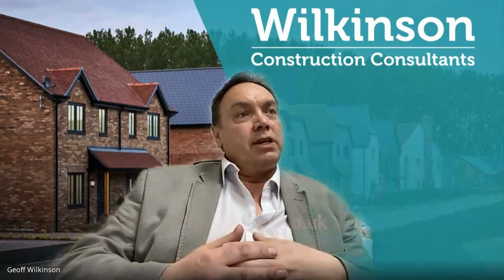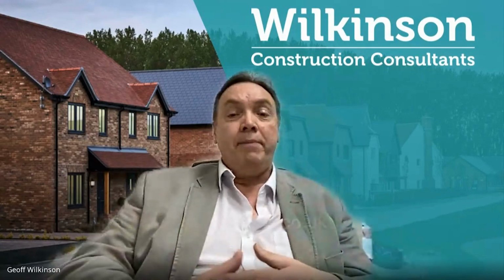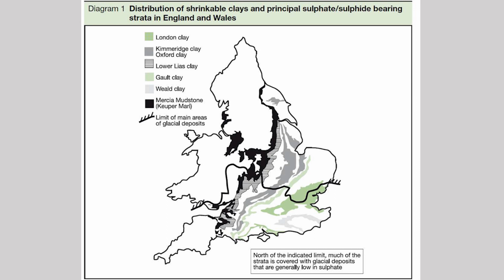One of the things that you quite often have is that the sites that are available are brownfield sites, so they'll have some kind of past history. It may be that they're adjacent to a landfill site where you've got waste and rubbish that's been decomposing over time, and there are risks associated with that. It might be a former coal mining area. All of this kind of information, if you take some time, even without having gone to the site, you can start to find out what else is in the area, what the history is, what type of soil you expect. So there are soil maps of the UK that you can find.